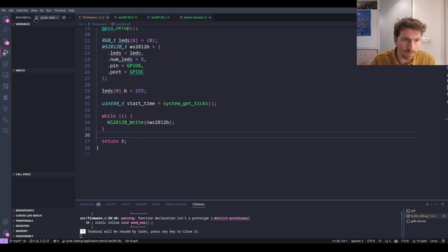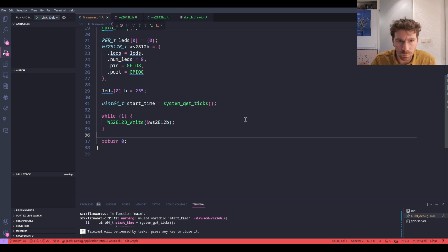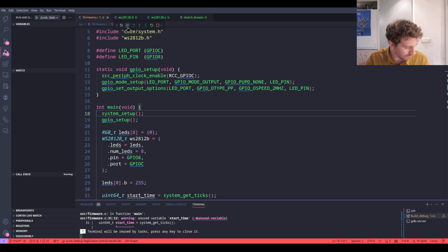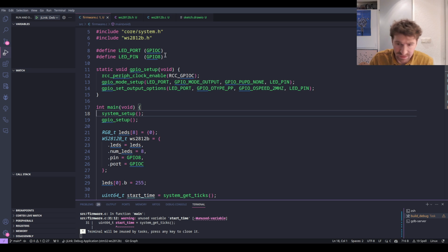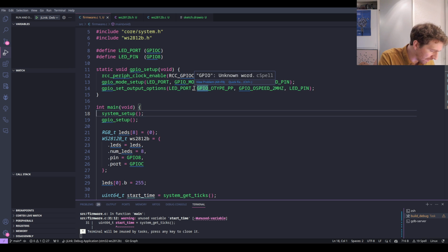And if I run this on the device, what we should see is the thing go blue. Wow, actually it's quite glitchy. So something weird's going on. Probably you won't be able to see this with the light in here. The first LED is blue, but the rest of them are sort of glitching out, and I'm really curious about why that is. Maybe we're sending data too quickly, but what I want to do is look at that on the logic analyzer, and see what kind of signal that looks like.